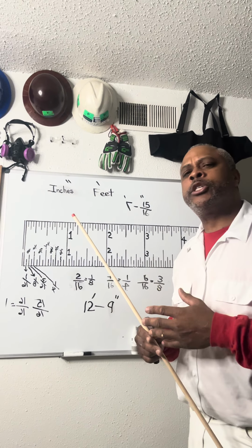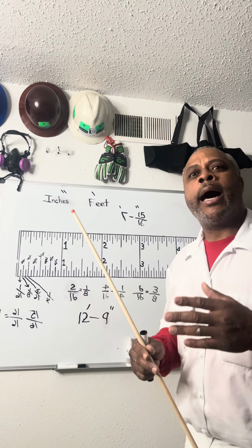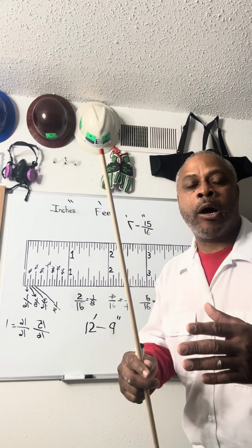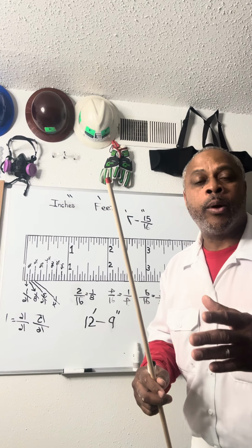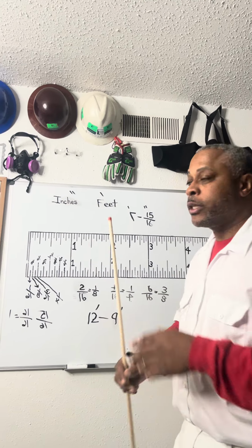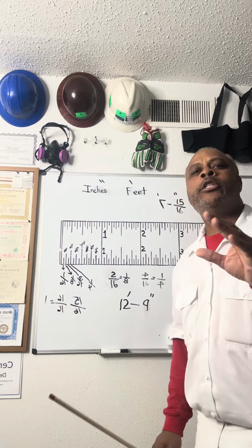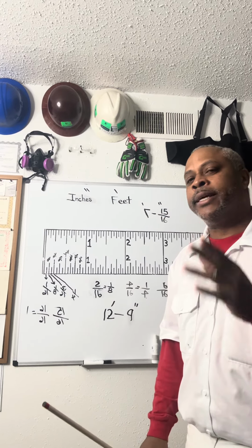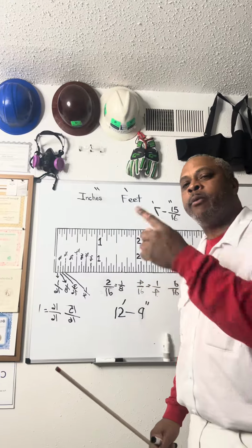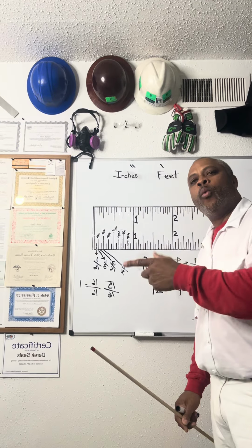Same thing, I'm going to do the Simpson, all the hold downs. How to lay out where all the Simpson stuff goes. So you can walk the job with the engineer on inspection and all these straps, hold downs, hurricane ties, you can identify them on the plan. You can have them implemented in the framing.